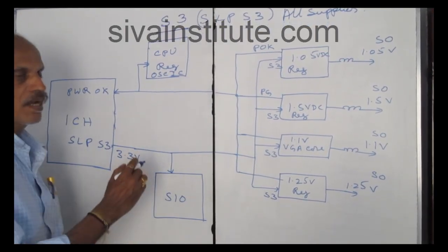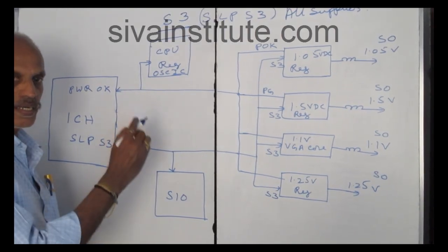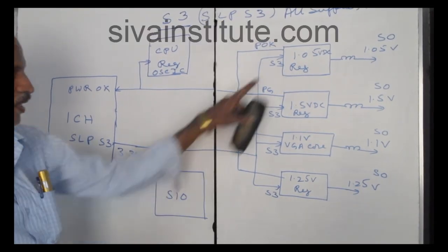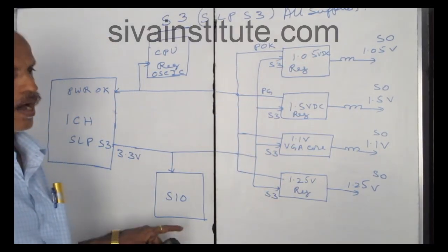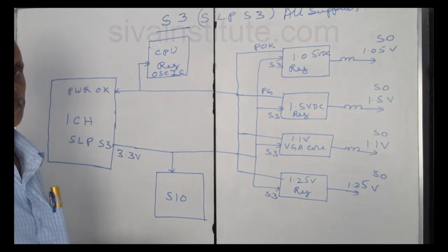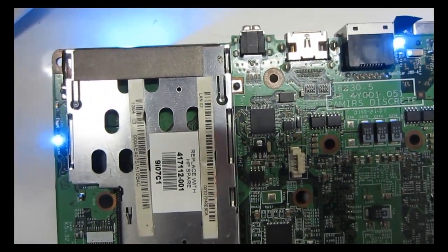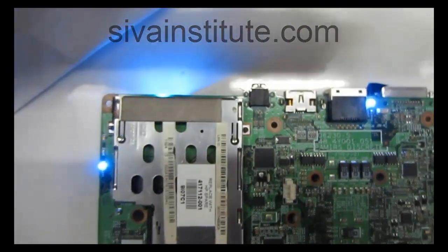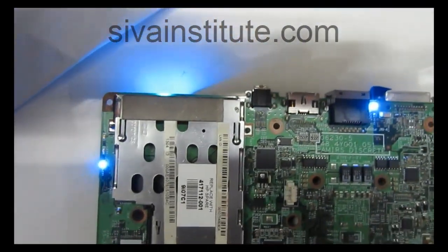After that, the CPU will start functioning. After the CPU regulator starts, when this voltage comes out, lights will be on, but a no display fault may come. Run power is okay. The motherboard lights are on. Now we will check run power.